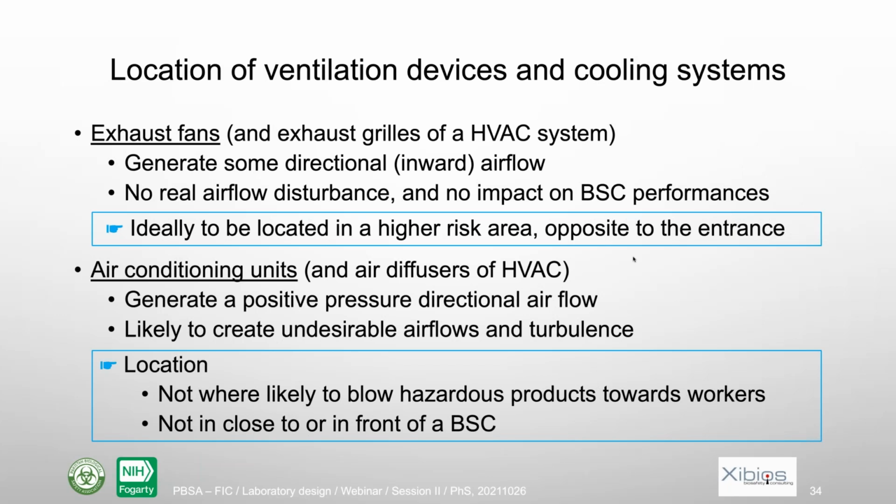On the other hand, if you have some air conditioning units and the air diffusing of a HVAC system or anything that blows the air, in that case, they generate positive pressure, but also they create some airflow disturbance. And because of that, an air conditioning unit or air diffuser should never be put close to a biosafety cabinet. They should never be put in front of workers if they are likely to blow some hazardous products towards the worker.